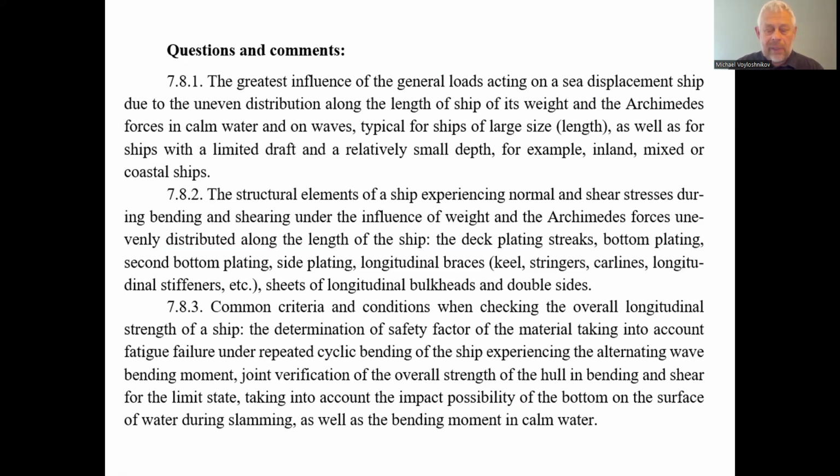And we can expect the general bending of ships and general shearing, as we did for the ship for transportation of liquefied natural gas, like a bunkering tanker for transportation of gas. 7.8.2, the structural elements of a ship experiencing normal and shear stresses during bending and shearing under the influence of the weight and the Archimedes force unevenly distributed along the length of the ship. The deck plating stacks, bottom plating, second bottom plating, side plating, longitudinal braces, the keel stringers, carlins, longitudinal stiffeners, etc. I mean, longitudinal connections could be sheets of longitudinal bulkheads and double sides.